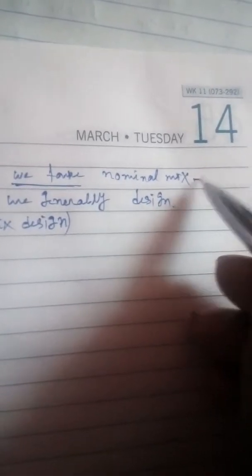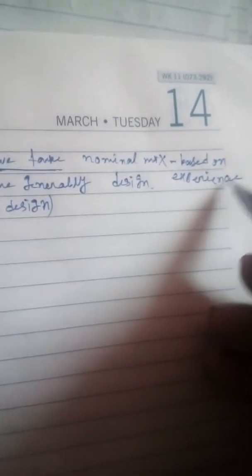For M10, the proportion is 1:3:6. If we take 1 bag of cement, 3 bags of sand and 6 bags of stone, then we can prepare M10 concrete. But in case of M25 or greater, we cannot say based on our experience. So what is nominal mix? Nominal mix is nothing but the mix proportion based on experience. But for M25 concrete or greater, we have to design it based on what type of sand, what type of aggregate, and what water cement ratio we are using in the mix. That's why for concrete greater than M25 we have to design the concrete. I will discuss mix design later.